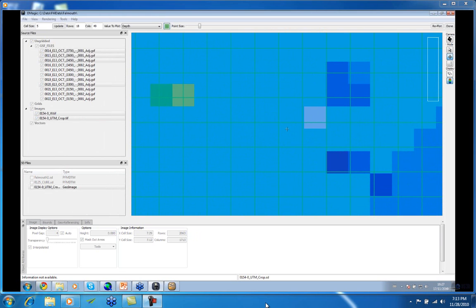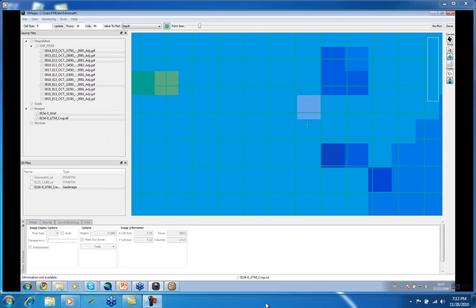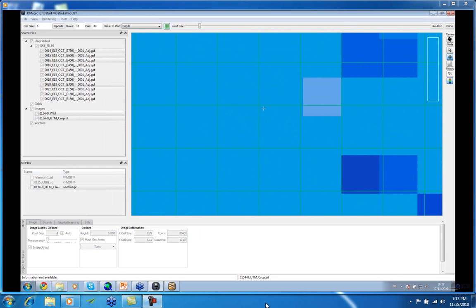So you have a weight diameter. A weight diameter of 1 will only take data within this one cell. A weight diameter of 3 means it's 3 by 3 cells. So it will take data from any of these 9 cells here, but the further away from this node here, the less influence it has on the data.